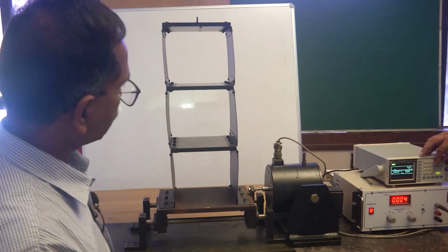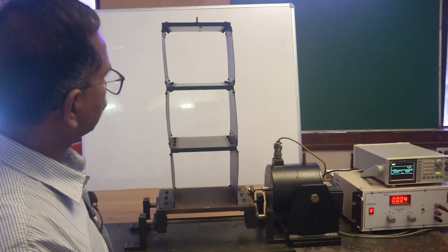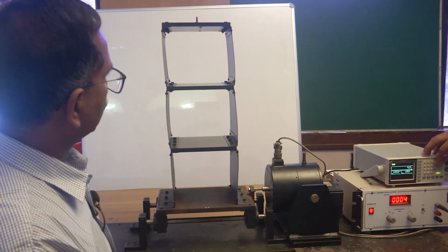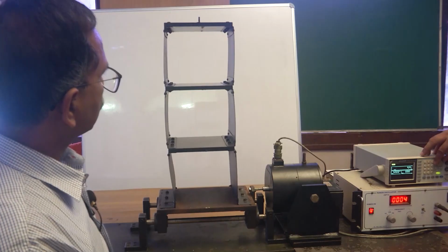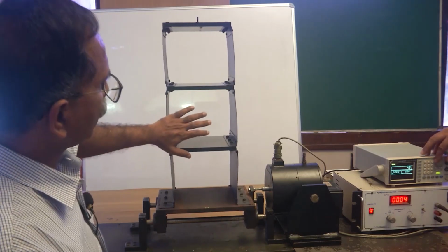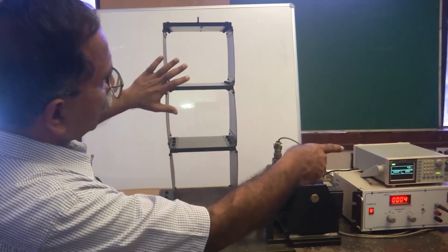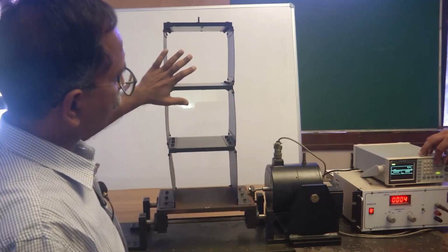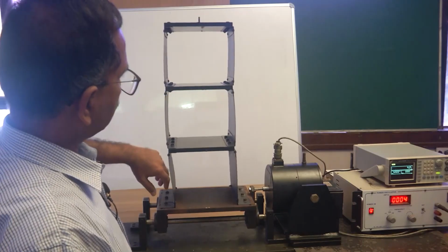So obviously the amplitudes compared to about 4 or 4.1 hertz have significantly dropped. Oh, this is increasing, right? So can you take it to 4.3? Let us check. Yeah, 4.4. So this is 4.5 hertz. Amplitudes are less as compared to at 4.3. Can you go back to 4.3? And probably here we expect large amplitude.